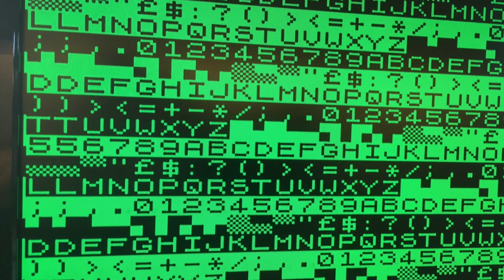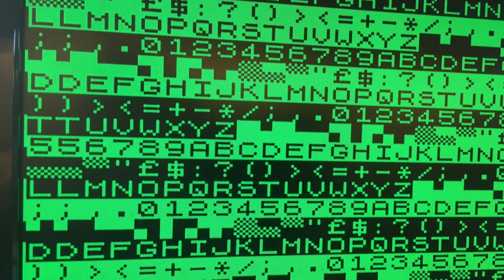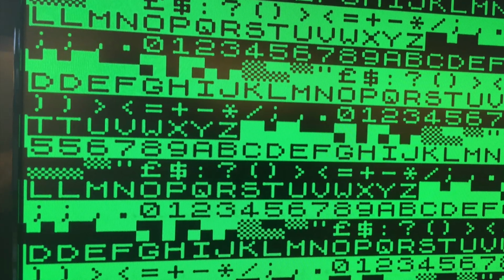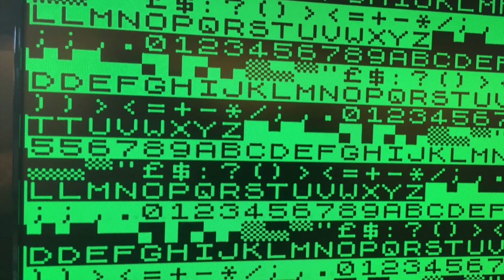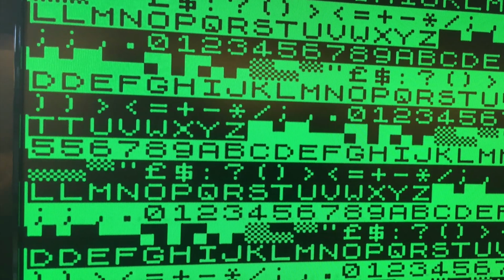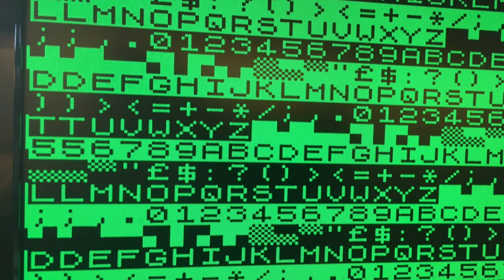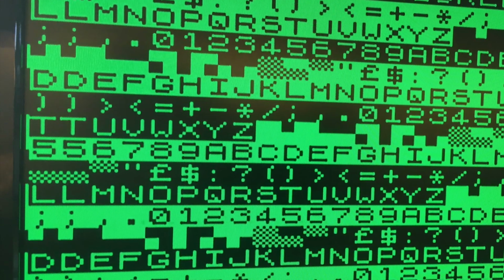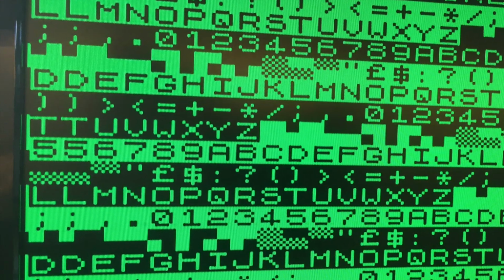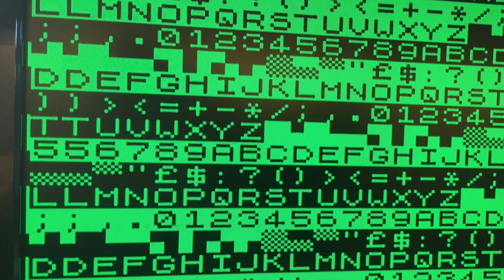Now, there is the other problem, which is still there. The first character of every line is dropped out, and the second one is repeated instead. But if you look closely at this picture along the extreme left edge of the image, you will see that there are also some spurious vertical lines there. And this, together with the character problem, suggests to me that we are having an initialization problem.